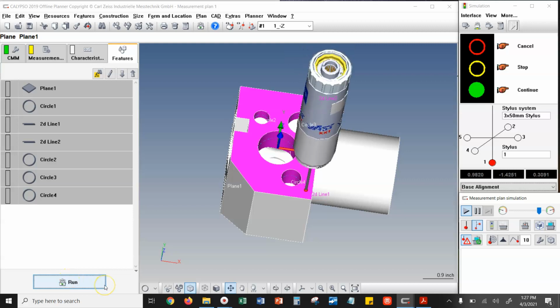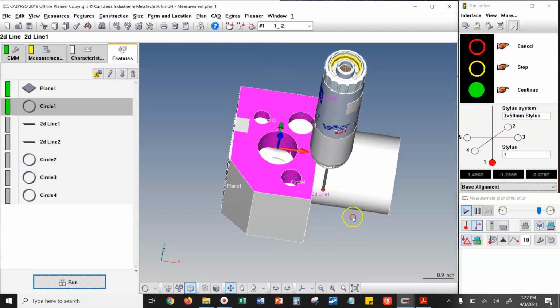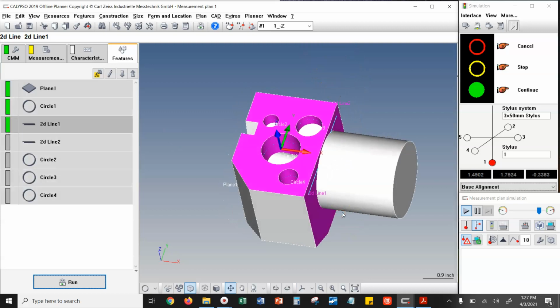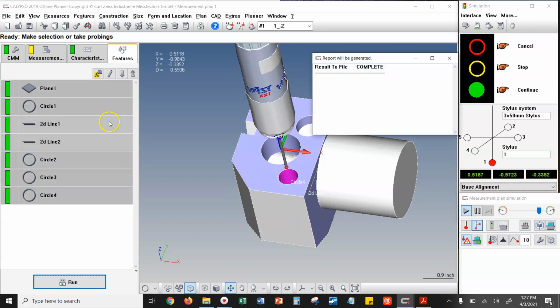And there we go. We're touching 1, 2, 3 points on the top, 1, 2, 3 points on that center hole. Notice how much better that runs with arc motion mode off. Touching 2 points on the right side, got a scan path on the other one. I'm going to have to go back and modify that strategy. Notice also how big the retract distance is on these features. That's all stuff we should probably clean up at this point, just while we're thinking of it.